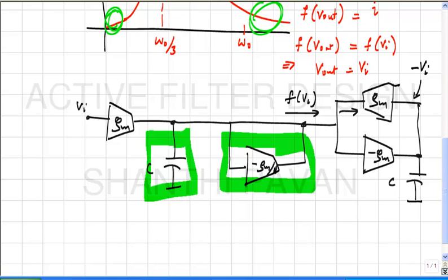Okay. So this is an important thing to bear in mind, because often you will find people quoting distortion at very low frequency, right? And you know, basically this is just specsmanship. You know, I can always choose a sweet spot in my filter and put in my tone and then show that, hey, look, this is great, right? But to be honest, you have to quote stuff roughly around omega naught by 3. It in fact turns out that for Butterworth filters, for example, if you plot distortion as a function of frequency, it will indeed kind of peak at omega naught by 3. Chebyshev also, if the ripple is small, you will kind of get stuff peaking at omega naught by 3, right? So that's in general a good place to put the input tone, right?